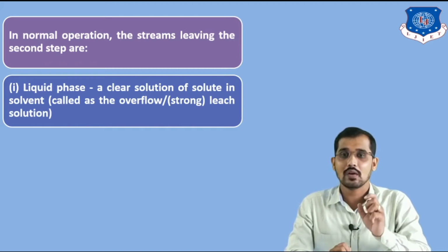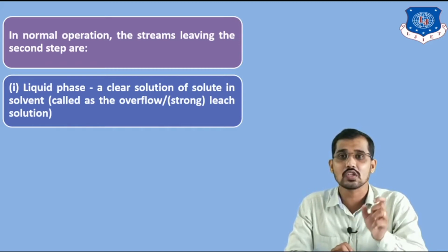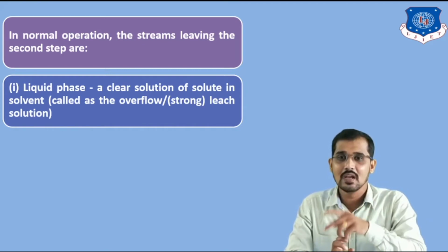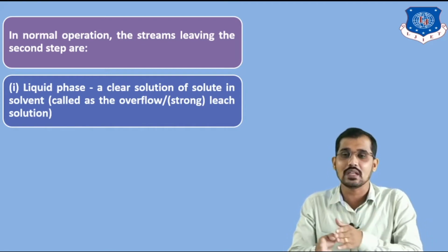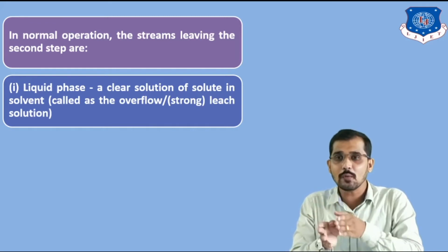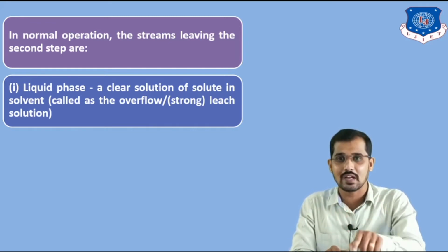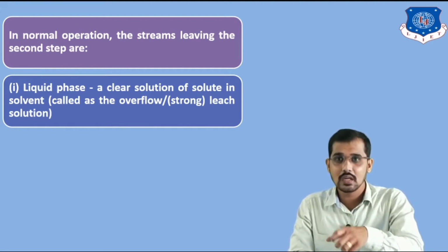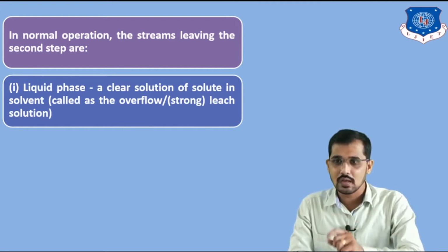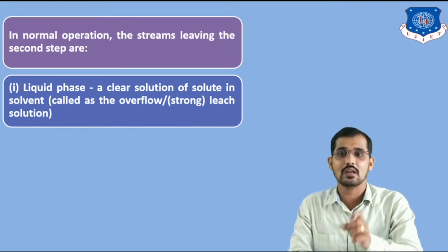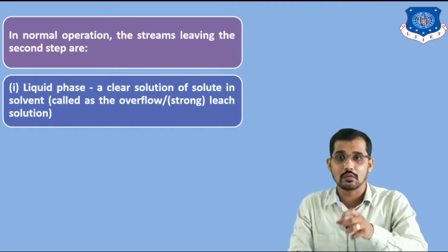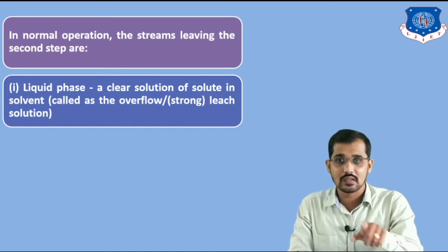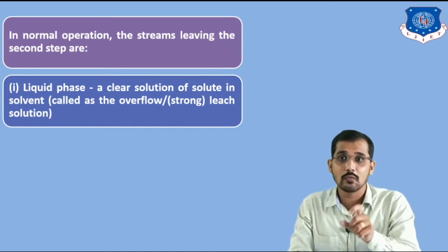You can see here, or I can say strong solution or leach solution. So this is your requirement, where you are getting two streams. First one is your overflow and second one is your underflow. So overflow, that stream is nothing but your requirement where you are extracting some valuable part of the solid in your liquids. Okay, so first one is the liquid phase where a clear solution of the solute which we want to remove from the solid particle present in the solvent, that is nothing but overflow,